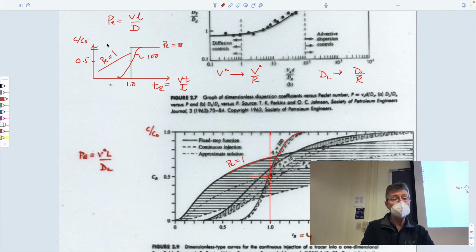So what we need to do is just modify Peclet number by including these two values. So Peclet number is velocity divided by dispersion. Velocity is divided by r. Dispersion is divided by r. So that's kind of convenient. We don't care. So the Peclet numbers won't change because this is going to be equal to 1. So when we do the calculation here for our new system, whatever the water is flowing at physically, that's the Peclet number we need to use for this advective velocity.